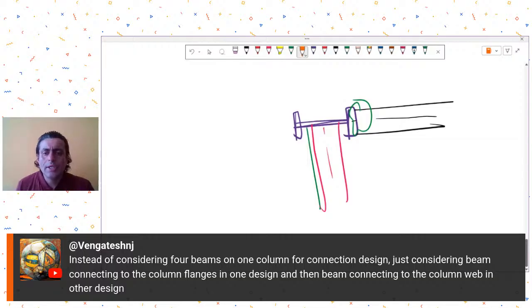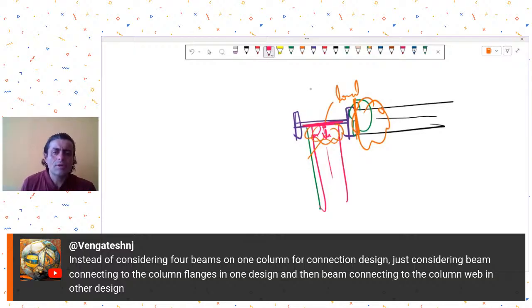So usually, see, there is this problem that the moments and shears on this side of the column may affect some of the local elements like web, when the connection on the other side is also created, and when you apply forces moments over here. But generally, because this side is your web, and on web you are anyway going to give a shear connection only, with shear connections it's not much of a problem.